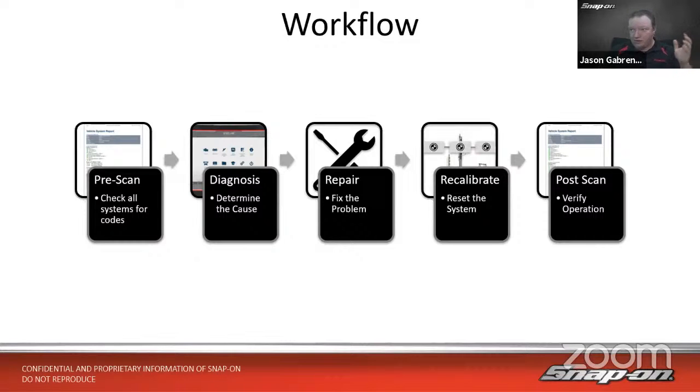Then once that's done, we'll go and do a post-scan. Post-scan dovetails or bookends really nicely with our pre-scan. Right? So we want to scan all modules again, make sure there are no codes left over in the vehicle, make sure the vehicle is in better shape than when it got to us. We want to send it back to the customer better than we had it before. And of course, we can share that as well.